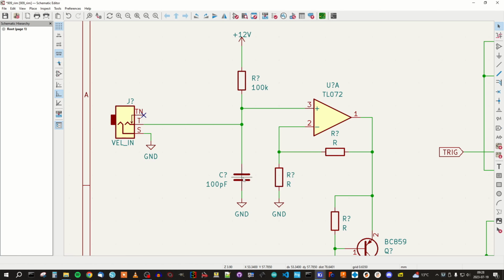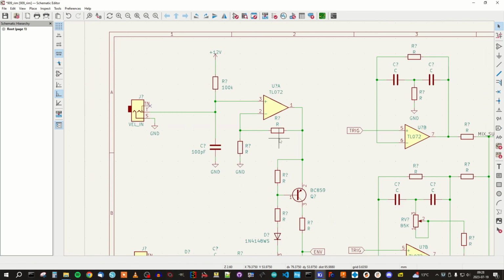All right, so before I continue to do the rest of the component values, I want to mention a couple of things. And you can see here on the connector, there is an X on that connection. And that is something that you do if you have an unconnected pin and you want to tell that this is okay, this should be unconnected. Then you can use this X symbol. Otherwise you will get an error or a warning when you do the design rule check, which we are going to do later on in this episode.